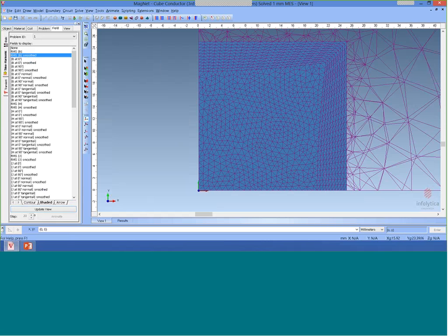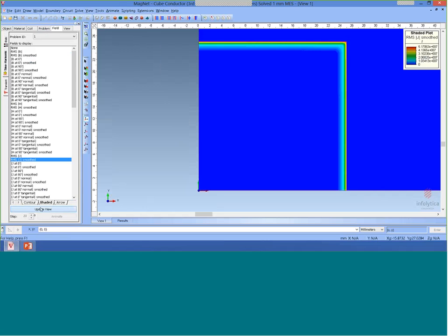And so you can see from this type of mesh, and if we look at the field for that again, we'll look at the J field because that gives you the nicest contrast. You can see it gives you a very nice solution on the surface, very smooth, and so on. For eddy current types of applications, actually, uniform layers are not necessarily the best.